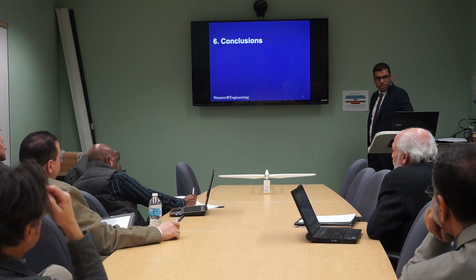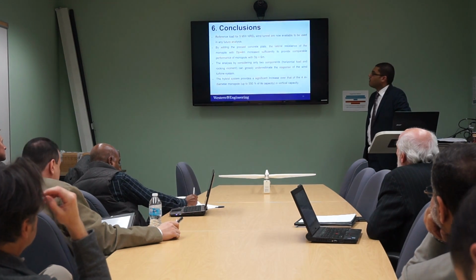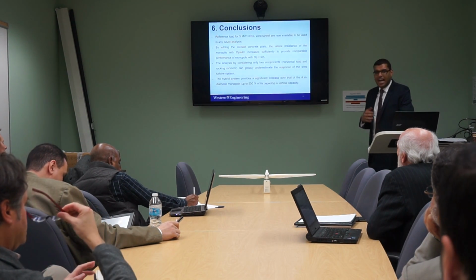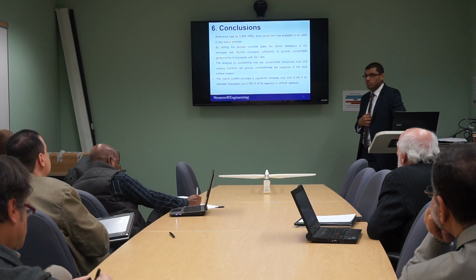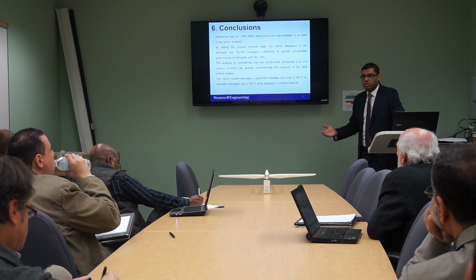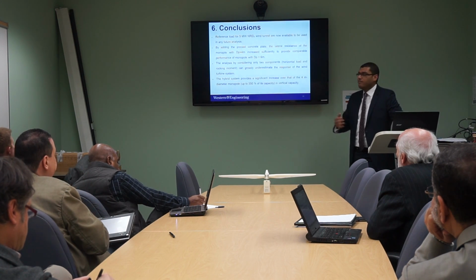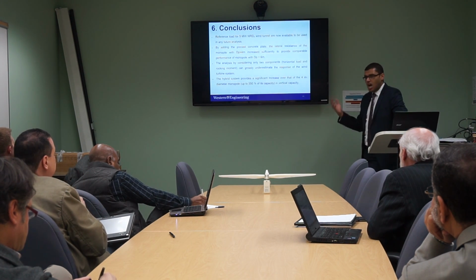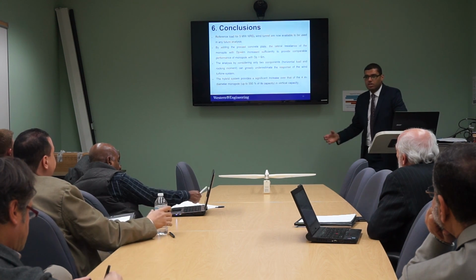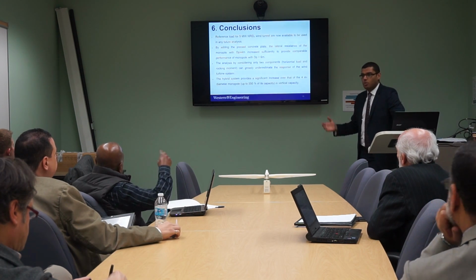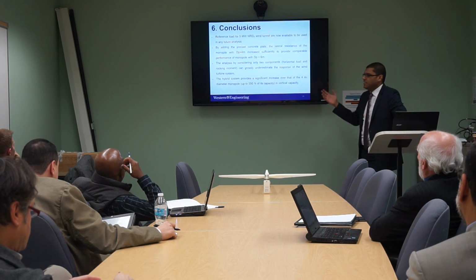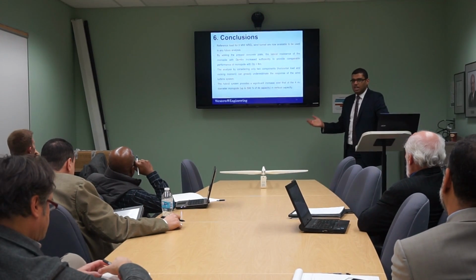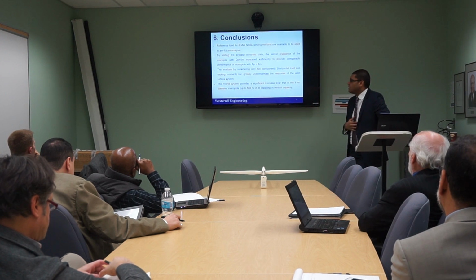So our conclusions: we will be able to provide actual 6 components of load at the base of 5 megawatt NREL wind turbine to be used by any researcher in the future design for the foundation. We provide our hybrid foundation system, which will be smaller, monopile diameter 4 meter compared to the monopile with diameter 6 meter. We have seen that we cannot just depend on 2 components in our analysis. We need to have 3 or 6 components.